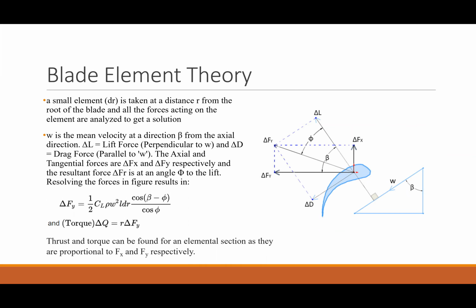Resolving the forces in the figure results in the equation shown, which is how the thrust and torque can be found for an elemental section, as they are proportional to Fx and Fy respectively.